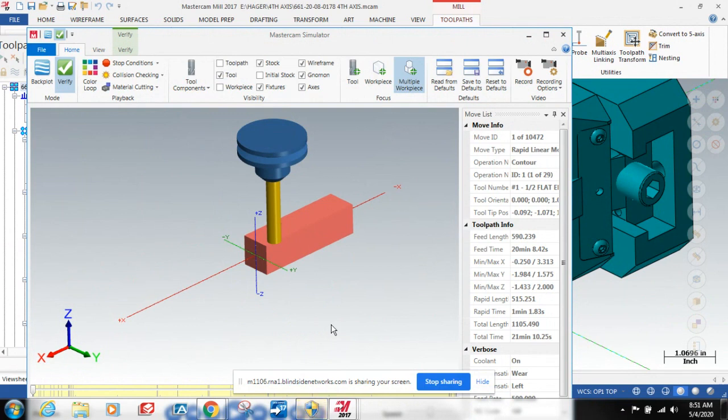Okay, so if there's a flat surface that you need to mill, you create a plane so that surface is perpendicular to the spindle. Right, so that gives you your index. It's going to index that plane as level, and then you can do the machining on it. It may actually be creating an angle on the part, but the machine's going to see it as a level surface.